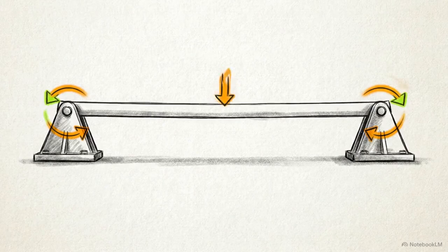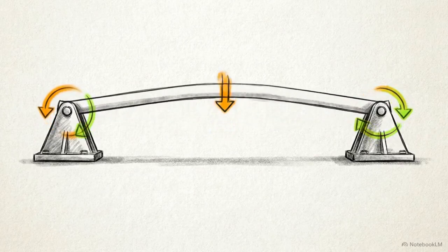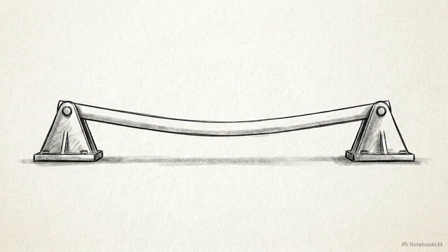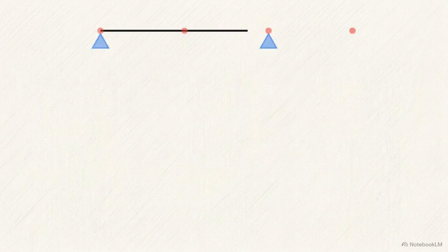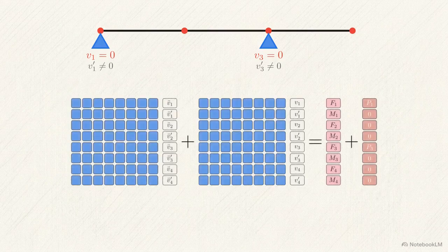To verify this mathematical procedure applies to all boundaries, we test it against a simply supported beam, pinned at both its left and right ends. Pin joints possess unique mathematical constraints. The vertical displacements are 0, but the angular slopes are permitted to rotate freely. Mapping these boundary constraints into the displacement vectors places our zeros exclusively at entry 1 and entry 5.